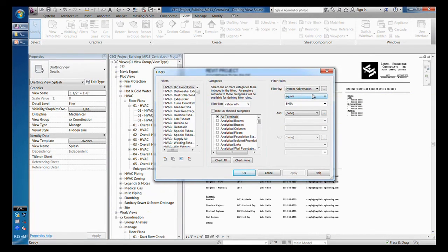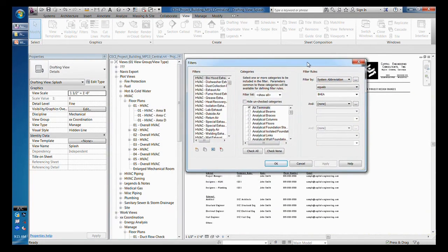Okay? So I'm sure that many of you still see benefit in that method. I decided that performance for my guys is priority, and we moved away from it. So now I'm no longer using system name begins with, and what I'm bypassing is that my guys don't create systems. We're letting Revit create the systems automatically.